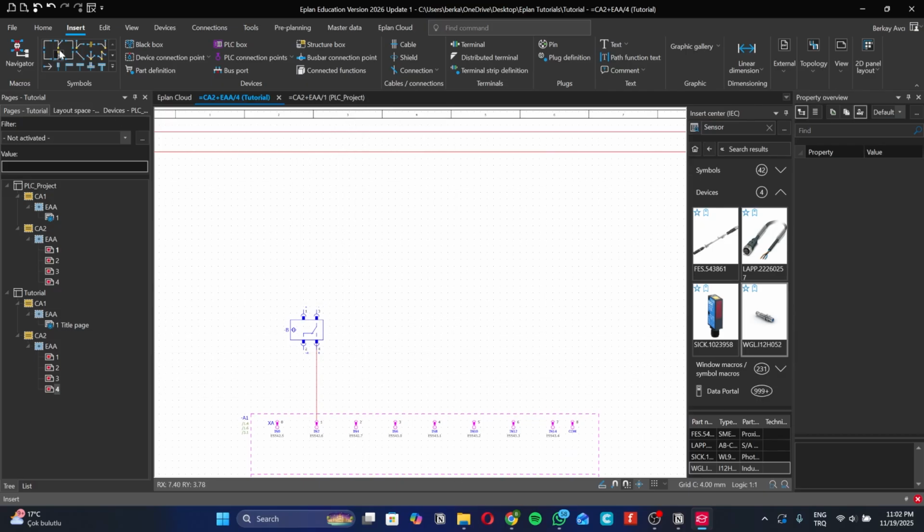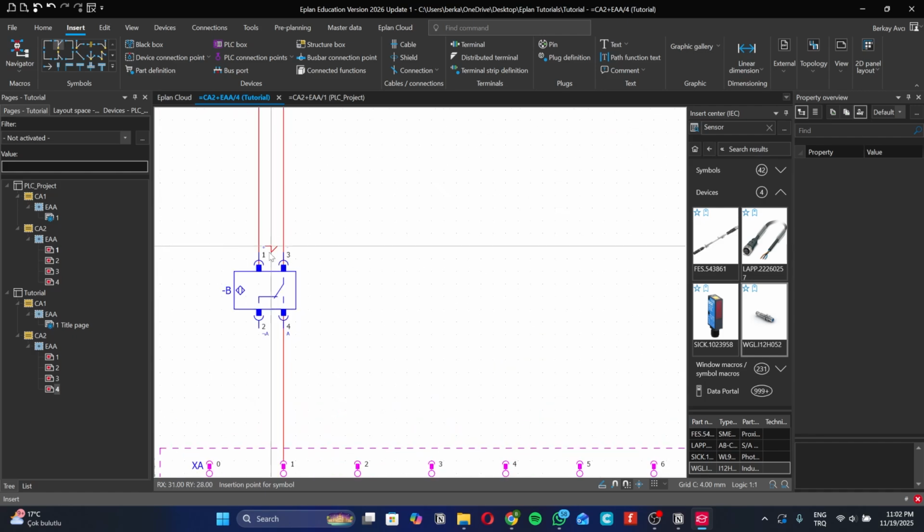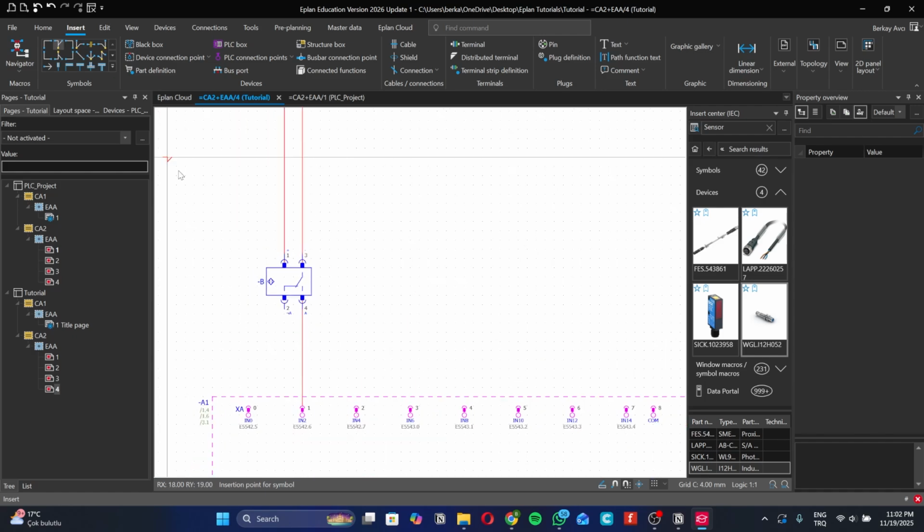But of course, for us to be able to detect those signals and change the position, we need to supply it power. So I need to give it 24 volts from the plus and connect the ground for the minus line. Now it works. I don't need to connect anything to this one because I'm just going to record it.